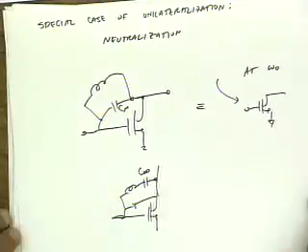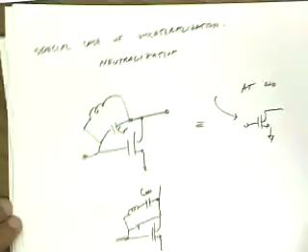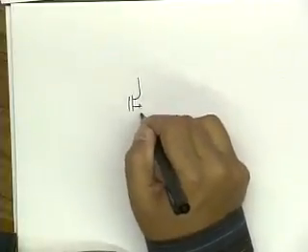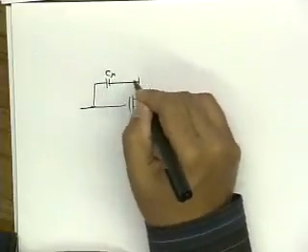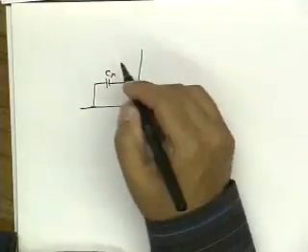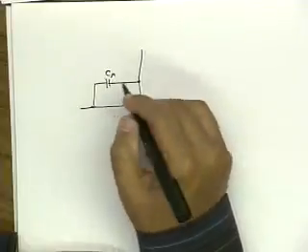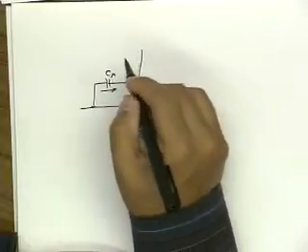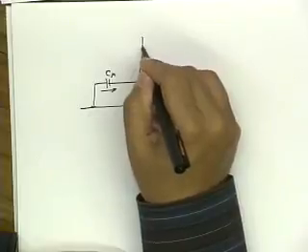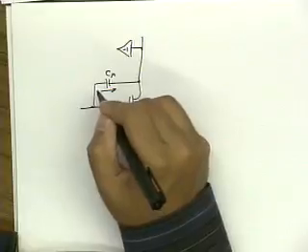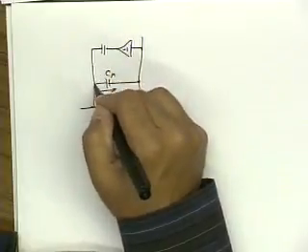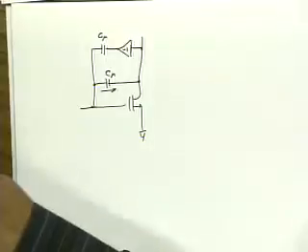And there's a couple of neat ways of, this is one way of neutralizing a device, but there's a really cool way of doing it if you have differential circuits. So here's another way of looking at neutralization. So I have this C mu, and somehow I want to cancel out this current. So what if I could somehow take this voltage, multiply it by -1, and also feed it back, right?